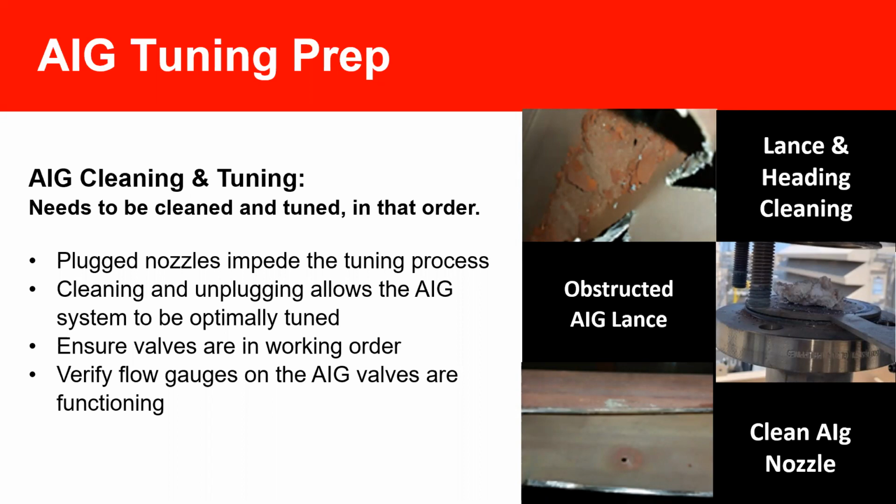So before we would want to get started tuning, we just want to make sure that the valves work, and often overlooked, that the flow gauges next to the AIG valves are functioning. We need to know the effect of a certain degree of valve move and how it impacts the system. And then the bottom photo, just for showing you what it should look like, is a picture of a clean AIG nozzle.